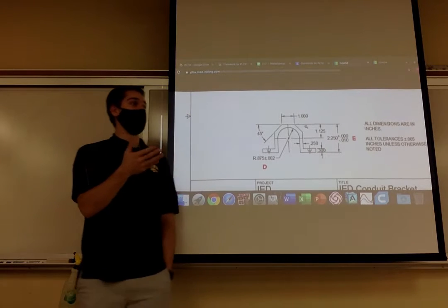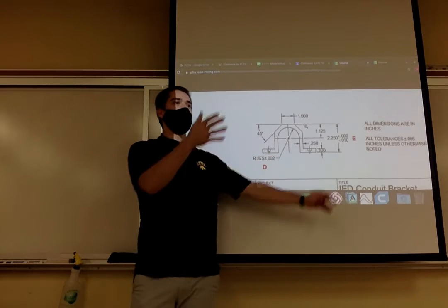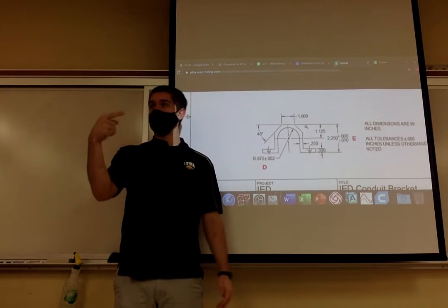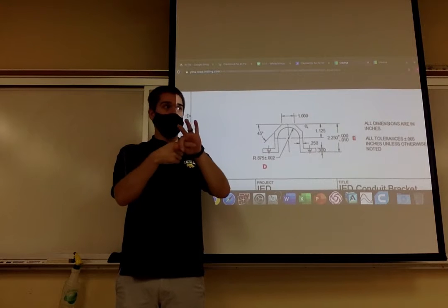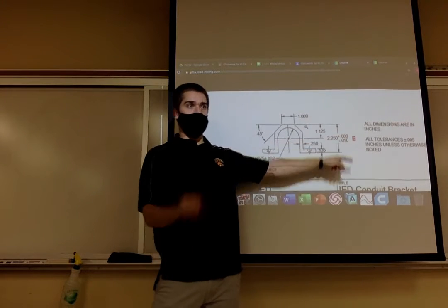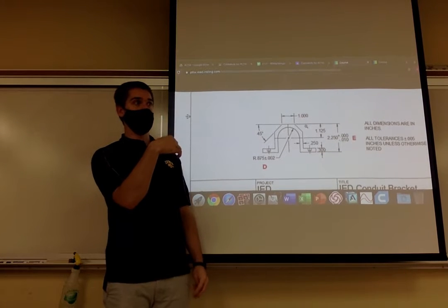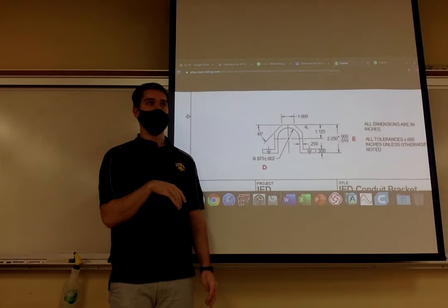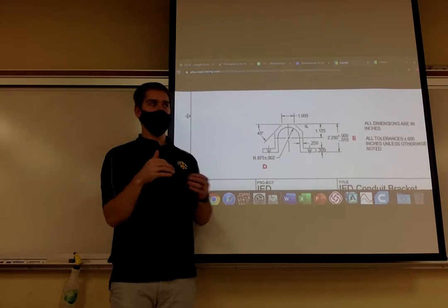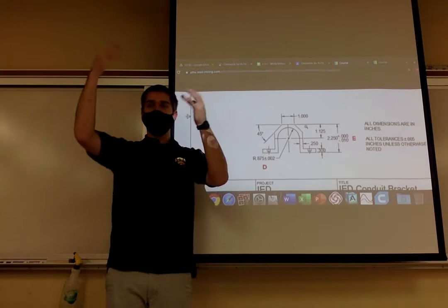Right. Another one, if you were being really precise, if you made your hinge and you have a pin that needs to go in the hinge so that it actually works, this is where you would place an upper limit on the pin diameter. If your hole is 1/2 inch, you'd want to give no tolerance on the pin on the upper side.